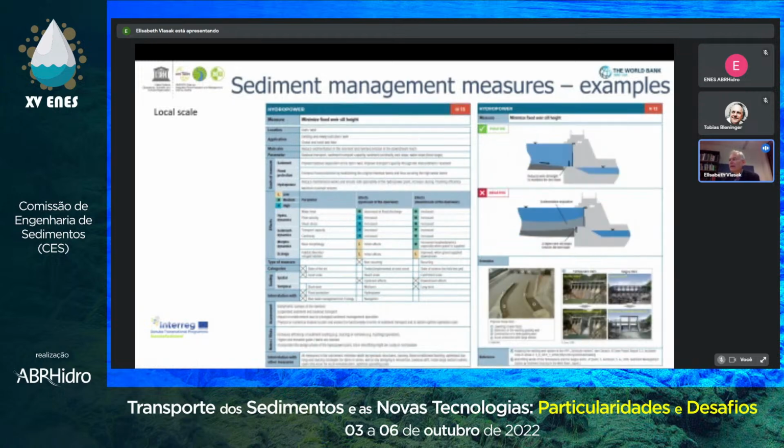The second planning point at the dam is the weir height, the fixed weir sill height. Here you see very high concrete, and the movable gates are small, and here the concrete is lower and the movable gates are larger. It's quite obvious: if I open the gates, the slope that develops is much higher here. Unfortunately, many power plants were built in this way, maybe because the movable gates were too expensive, but then the slope doesn't support your flushing.